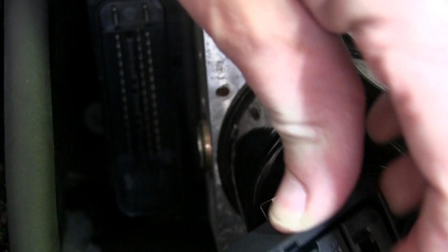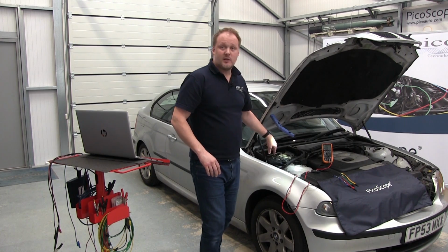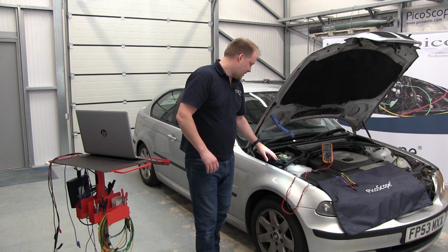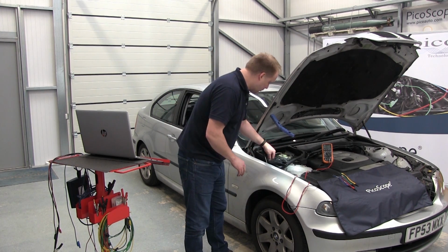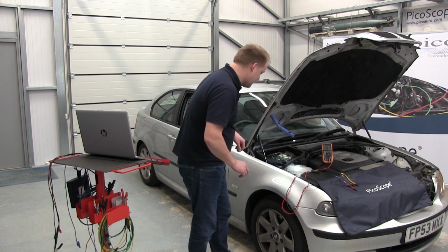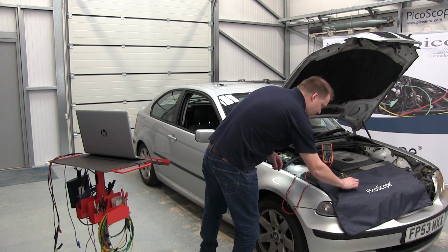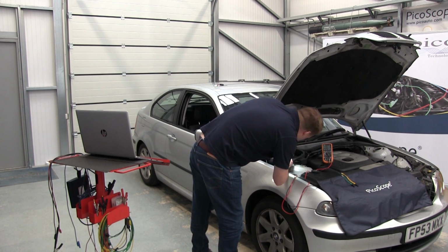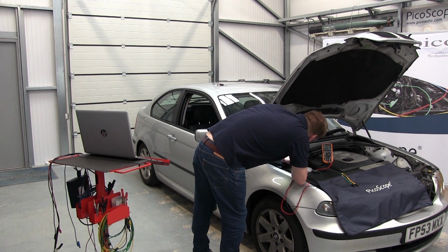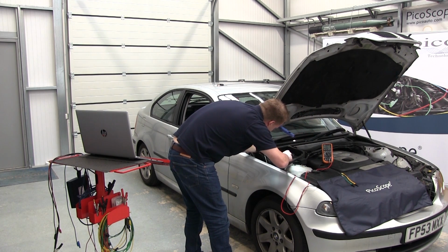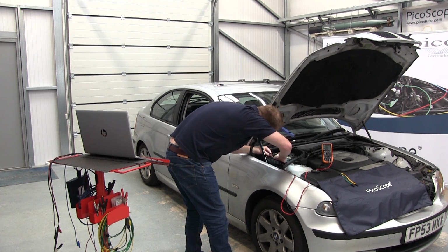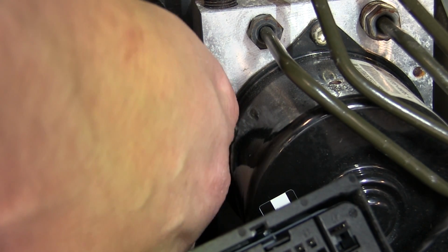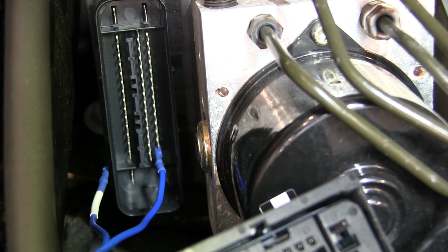and there we go. Knowing that we've got one termination resistor in the module and another resistor at the other end of the line somewhere, we're well placed to check for the resistances at the two ends. So again, we'll use breakout leads for convenience. So I'll look at the ABS control module first. So bear with me whilst I get these probes in place, or these connectors in place. Right, lovely. That's the first one in.